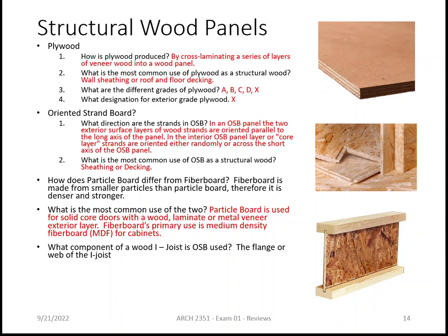No. Okay. This is an I-joist. Okay. This middle portion right here is called the web. Okay. It's made out of OSB. These two top portions are called the flange. Okay. And those two are usually made out of LVL or PSL. Okay. Structural composite boards.